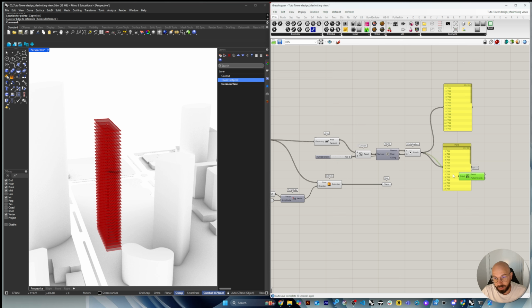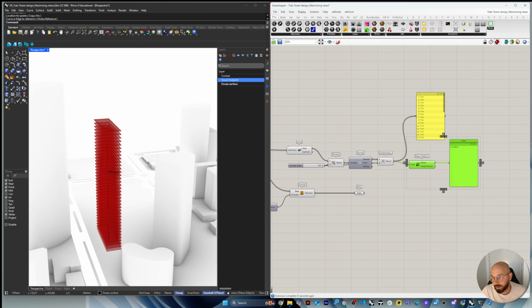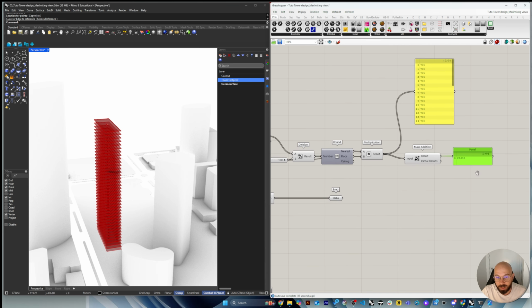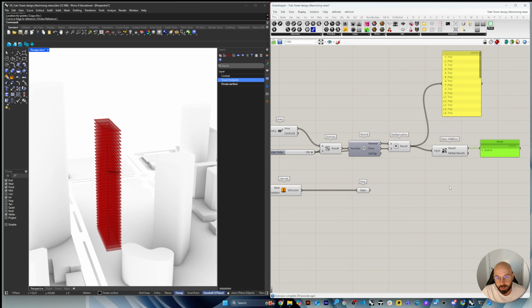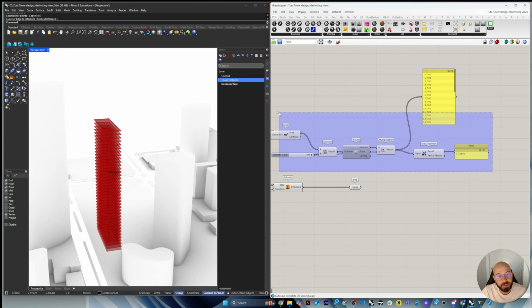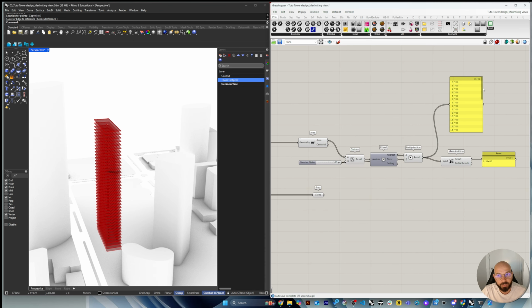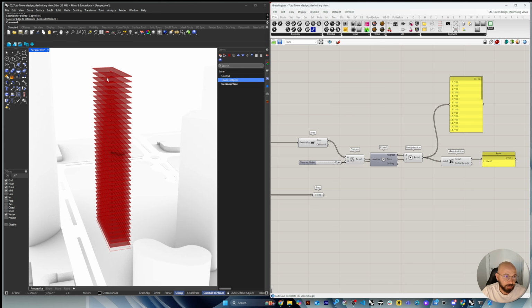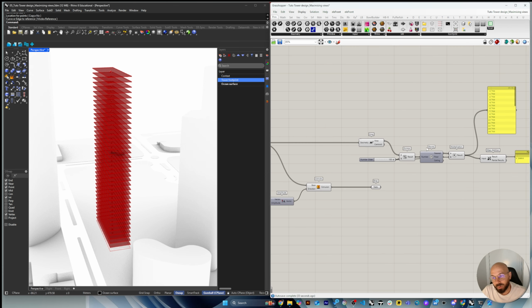Now there's one thing that I can do here, which is a mass addition, and I can add all those results here. And by doing so, I have my total floor area. The problem with this one though is it's measuring, of course, from 0, so from this one 700, but it also calculates and measures the roof here. So we want to remove the roof.